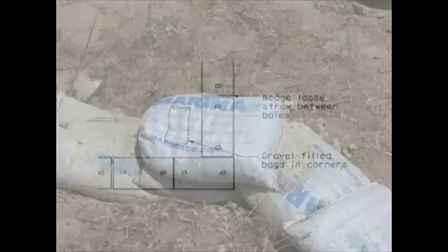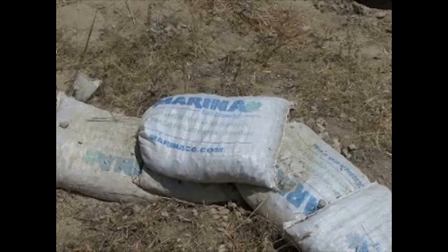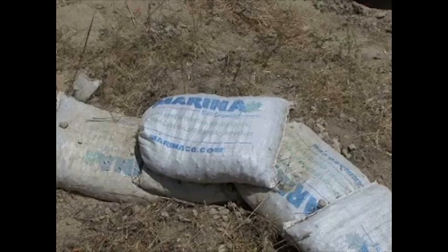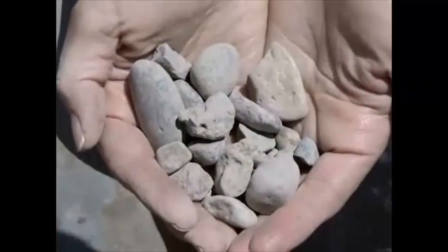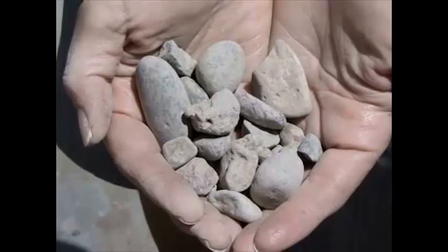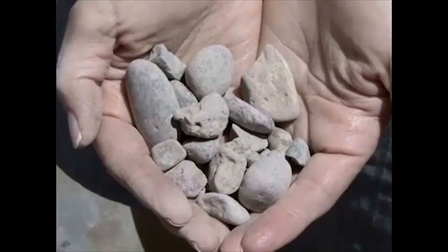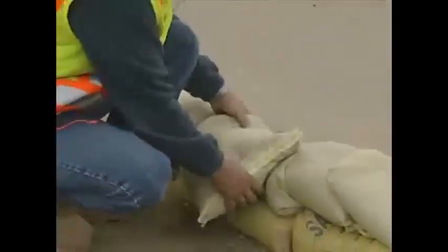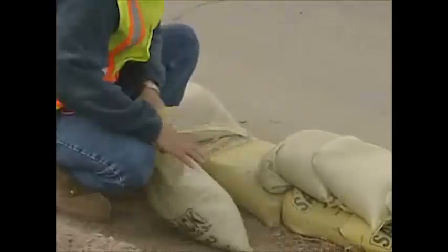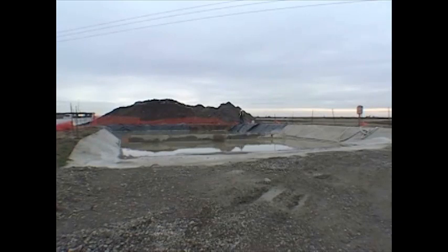Gravel bags must be between 24 inches and 32 inches in length and between 16 inches and 20 inches in width. The gravel must be between 3/8 of an inch and 3/4 of an inch in diameter and must be clean and free from clay balls, organic matter, and other deleterious material. Gravel bags must be between 30 pounds and 50 pounds in weight. Below grade facilities are constructed with a minimum length and width of 14 feet and 9 inches and include an earthen berm along the perimeter.